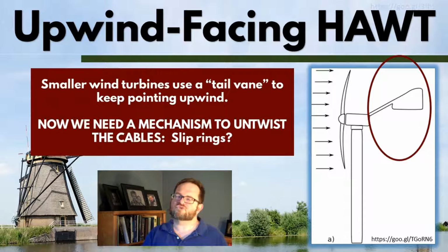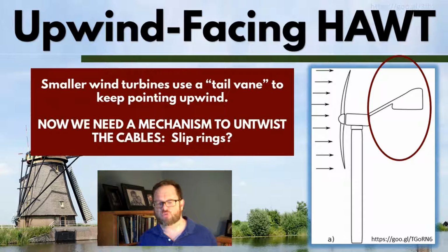So you're using this sort of slip ring technology. In general, that's not a great choice if we're talking a very large turbine. That kind of slip ring technology is not going to work if we're talking much current. A small demonstration wind turbine at a school or something, that would be fine. But for something commercial, that kind of slip ring technology is not going to be the tool for the job.